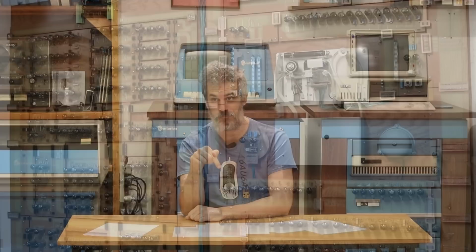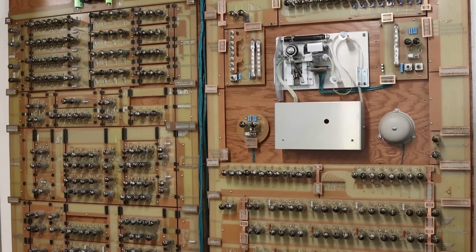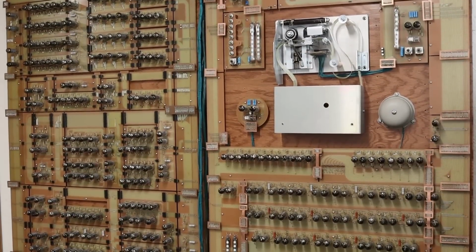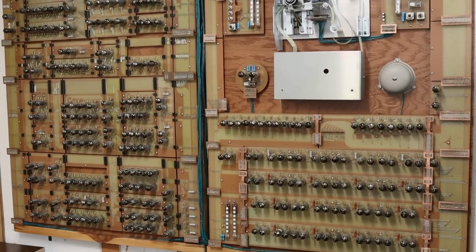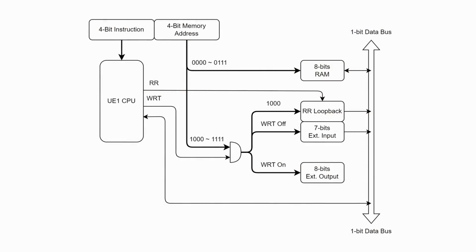Now it's important to note that every instruction is executed, but whether that instruction modifies memory or not can be controlled with this IEN and OEN register. Now, this is just the processor portion. This is just that left half of the board, and this by itself is pretty useless. So we need to put it in a part of a larger system.